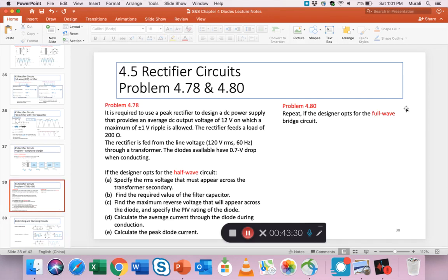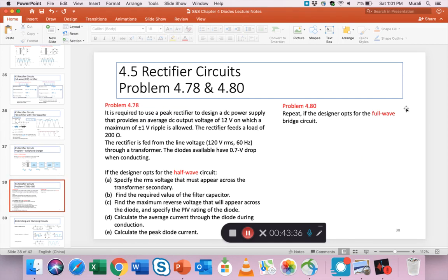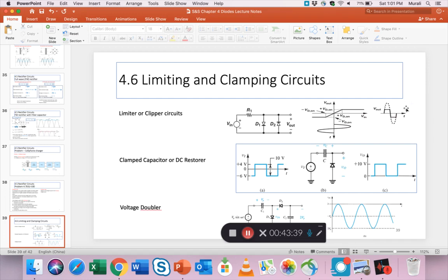Yeah, so that was pretty much it for rectifiers. So we studied the half wave and the full wave rectifier. We looked at the center tap full wave. We looked at the bridge full wave. Then we looked at those rectifiers with capacitors. Now, without the capacitor, the ripple is significantly high, right? The ripple is almost equal to the output voltage, it's all rippled. But with filters, the output voltage has a small ripple, and so it's still there.